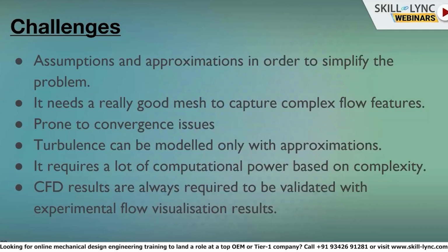Nowadays a lot of variations are coming: different turbulence models, different wall functions, different numerical schemes. You might be trying to solve a complex phenomenon using some complex schemes, and then you will end up with a convergence issue. Then you may need to fine tune the model and get it right. So choosing those parameters is also